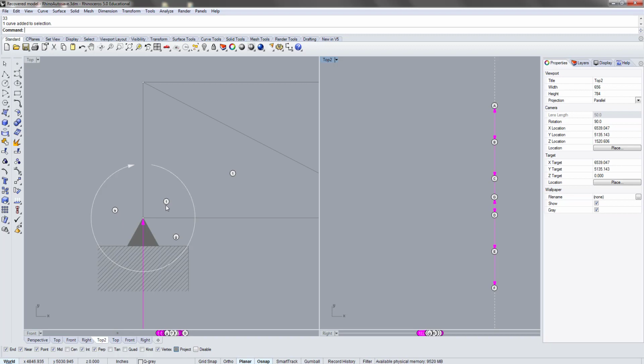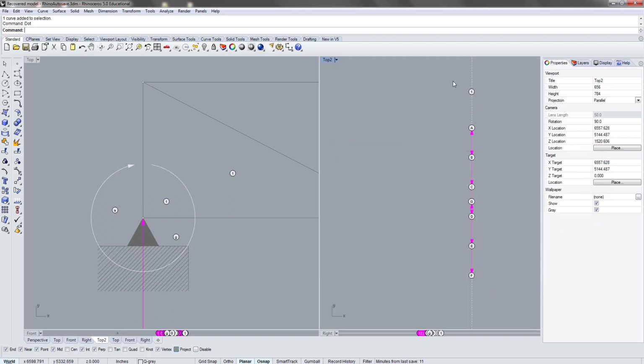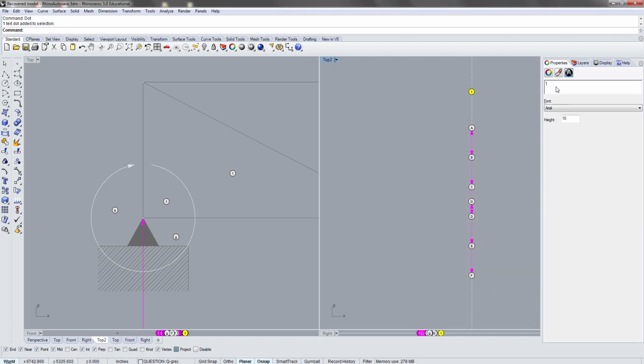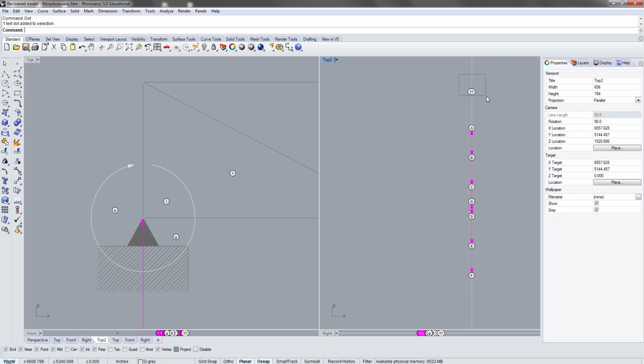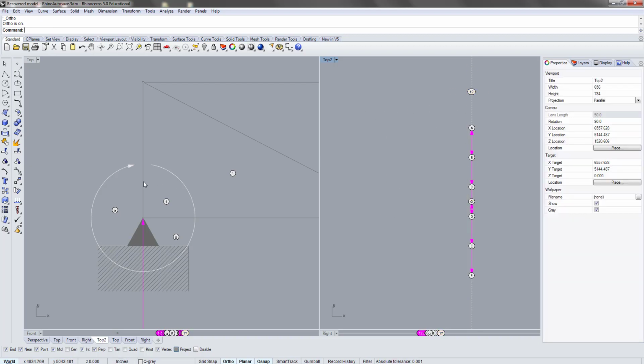So there's going to be a vertical force called A1. It's going to start from point A and end at point 1. Point 1, we don't know where it is yet, so I'm just going to put it as a question mark, and all we know is it's going to end up somewhere along this vertical line that passes through point A. So that's all we can tell from that vertical member.